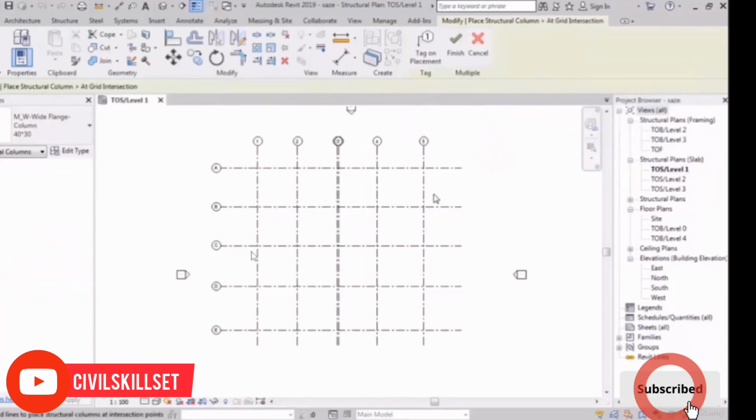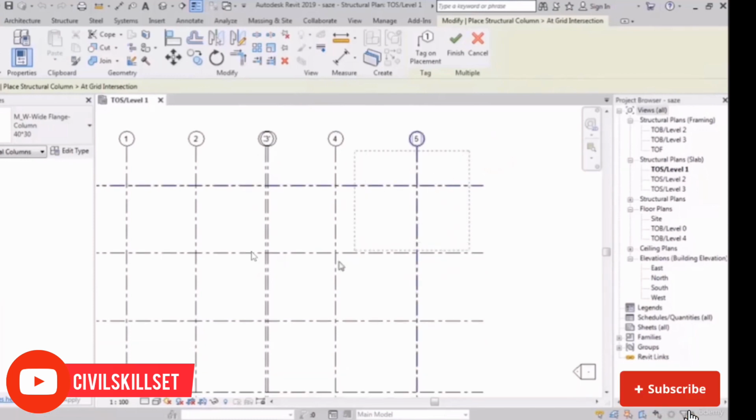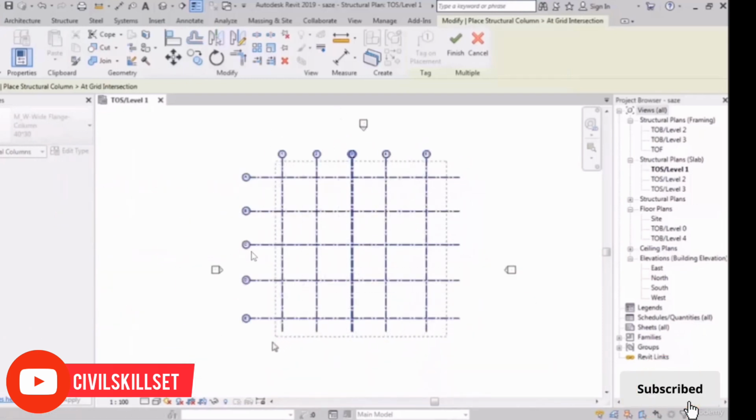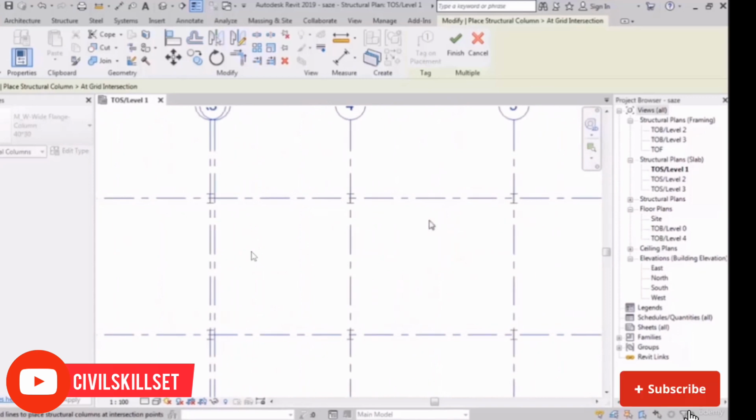So, at first click Add Grid, and then we place the columns. Now, answer this question. If I open a box, how many columns does it show? That's right, 4, because it's the intersection of these 4 grids, right? And if I open a big, let's say a complete box, all of them are shown. But if I zoom it a bit, you can see that the columns are placed vertically.